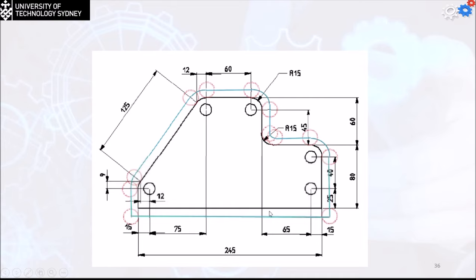Then we are going to define the first point. That means I have to do some feed cutting. That means G01 to the next point, and in this case the Y is not going to change, the X value is going to change. So G01 where the X is equal to the distance from this point to that point.